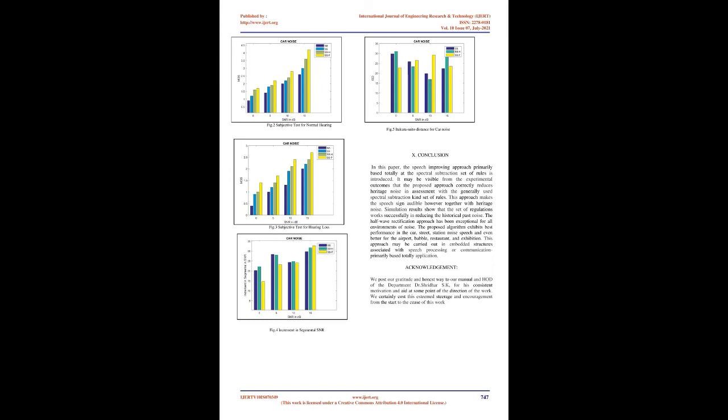RC equals the autocorrelation matrix of the clean speech signal. Note: LPC, linear predictive coding, is the method used mostly in audio signal processing and speech processing for representing speech. Spectral envelope contains information of the signal or speech. The lower the value we get, the better the proposed method's signal quality, and the lesser the speech distortion that occurs. For proper analysis, different SNRs at different noise environments are used. LLR value must be in the range of 1 to 2, which indicates the proposed algorithm gives a good enhanced speech.